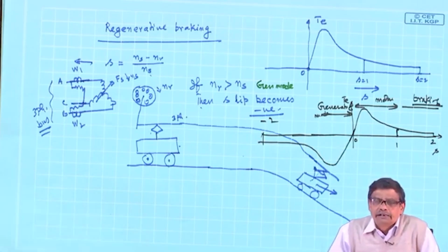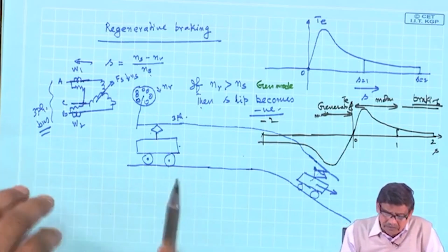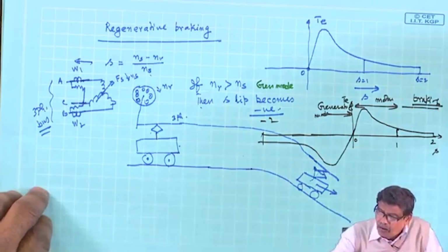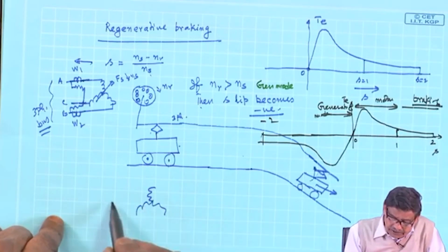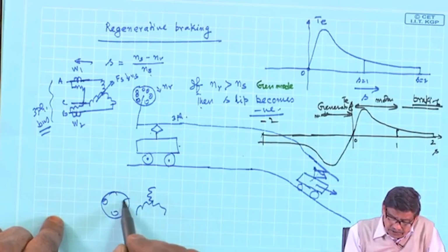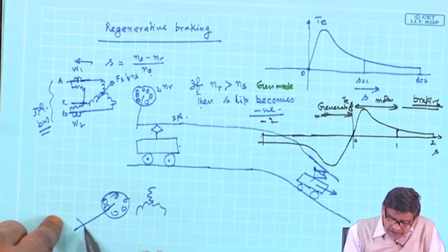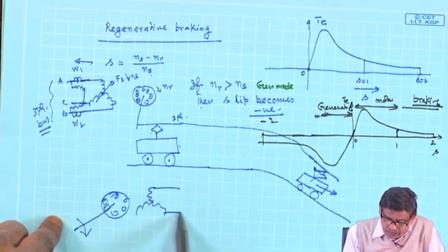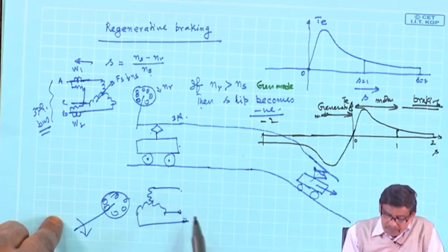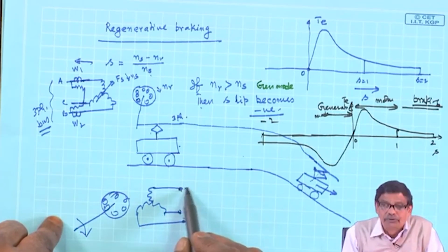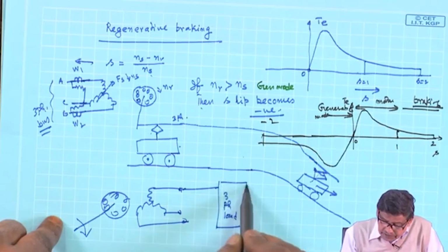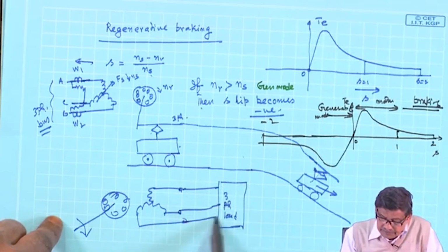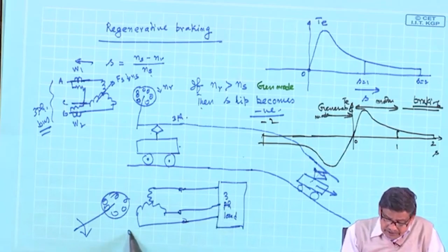What is a generator? I will have some field control, that is I will try to operate this induction motor, this is the rotor, cage or whatever it is. I will drive it by a prime mover, can I expect some voltage to be generated? And here I will connect the load, 3-phase load. See, distinction must be made between these two cases. It is induction generator.